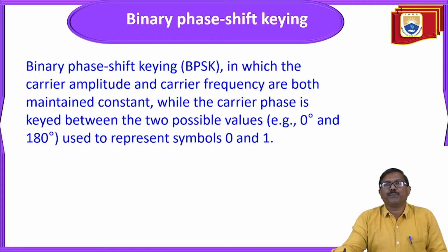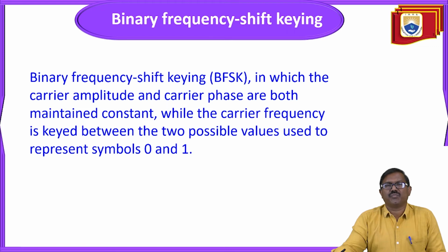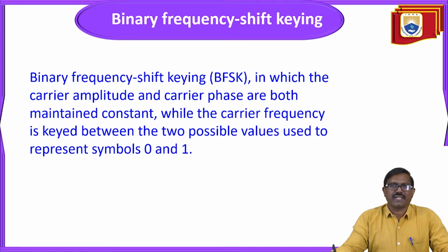that is BPSK. And another one is BFSK, binary frequency shift keying, in which the carrier amplitude and carrier phase are both maintained constant, while the carrier frequency is keyed between the two possible values used to represent symbols 0 and 1.